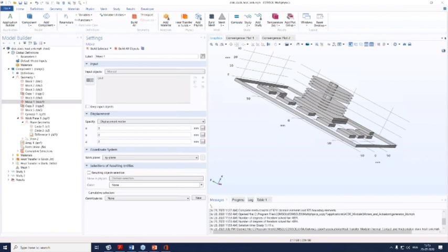Whereas if the geometry that you have drawn is the same 10 by 10 by 10 geometry, but rather than starting from 0, 0, 0, you are starting at, let's say, 10k, 10k, 10k, that is the starting corner point of that cube, then in that case, the absolute tolerance is going to be 1e-3 times 1e4. That means you will have an absolute tolerance of 10.